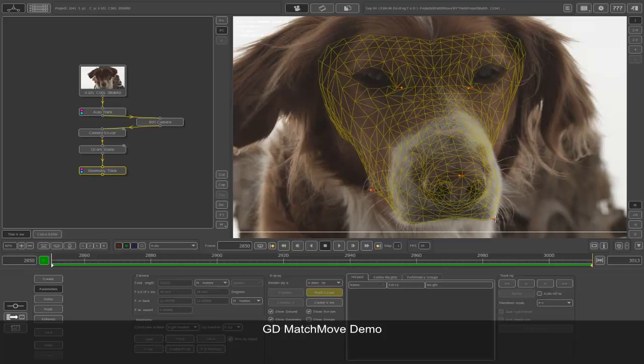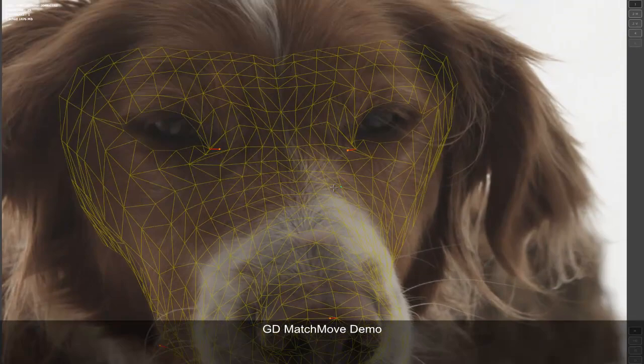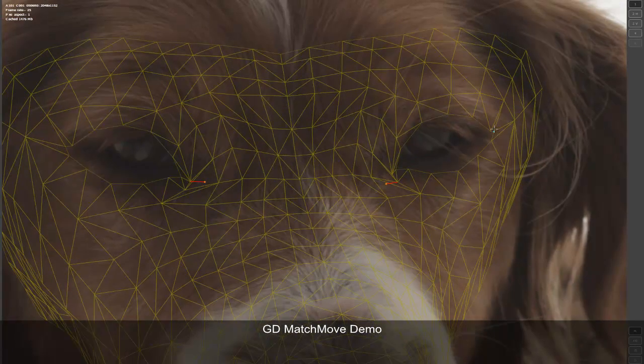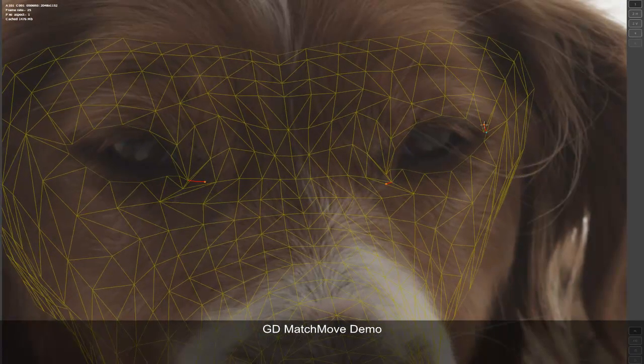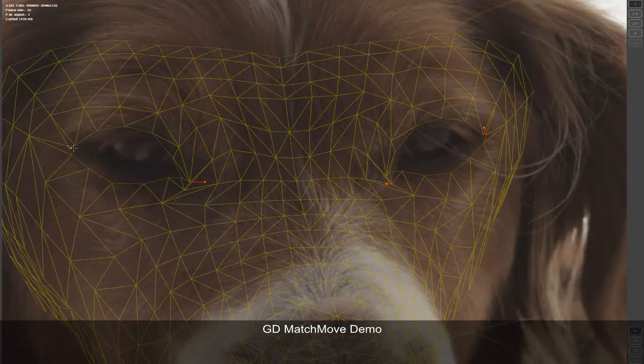You can add in as many pins as you want, and if you have added a pin which is not required, I can go on top of it. Once it's turned blue, I can hit delete on the keyboard to get rid of it. So I can just zoom into a full viewer, the shortcut for it is Alt F. I can set it up perfectly along the mesh.